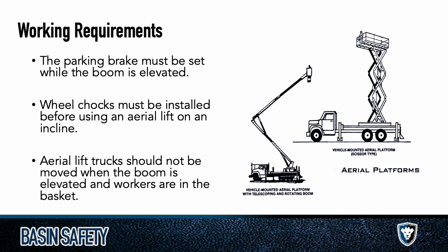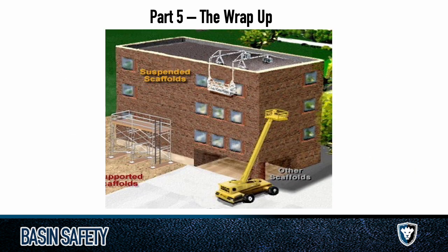Working requirements. The parking brake must be set while the boom's elevated. Keep that in mind. Now, a lot of them do that automatically, right? Once you stop and you start moving the boom, the parking brake on the wheels automatically sets. If you're on an incline, just like a forklift, you need to use your wheel chock. And then aerial lift trucks should not be moved when the boom is elevated. Not a good idea. Don't do it. Bad practice. Terrible, terrible idea.